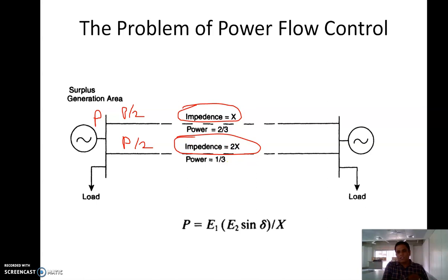Now this is just a two transmission line network which is shown to you, but in reality the power system has n number of lines which are connected in all kinds of topologies, and the power keeps on flowing in this way just based on the impedance. Of course, we have some level of control by using the tap changer at the substations.